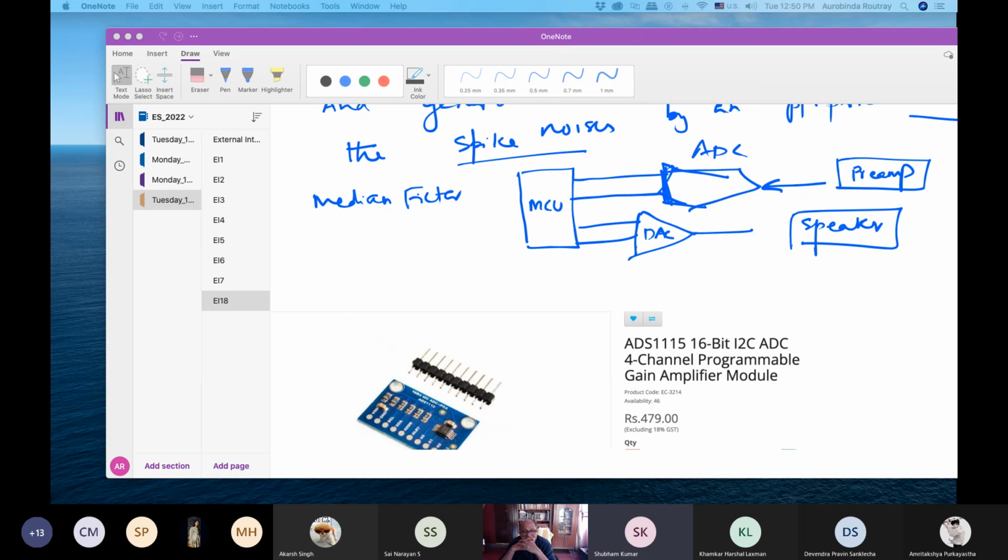Yes, sir. But here our only job is this. No median filtering is there. So while the ADC is doing its job, you should do median filtering. Because you get samples fast, 3 samples you will get fast, so it will store in 3 registers. Then the computation will start. You find the median, send it, then again read the ADC, wait for the ADC. This waiting for the ADC will not be there if you use an interrupt. That's what I'm saying. Okay, yes, sir. A good question. Any other question?